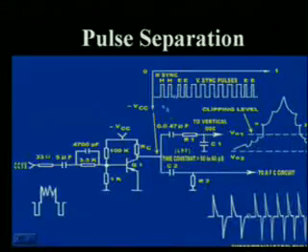I have already told you that the horizontal oscillator and vertical oscillator may not accept the separated sync as such. Then what do you have to do? By integrating the composite sync, we get vertical sync in this form. If the separated sync is differentiated, we get a horizontal sync pulse of this shape.